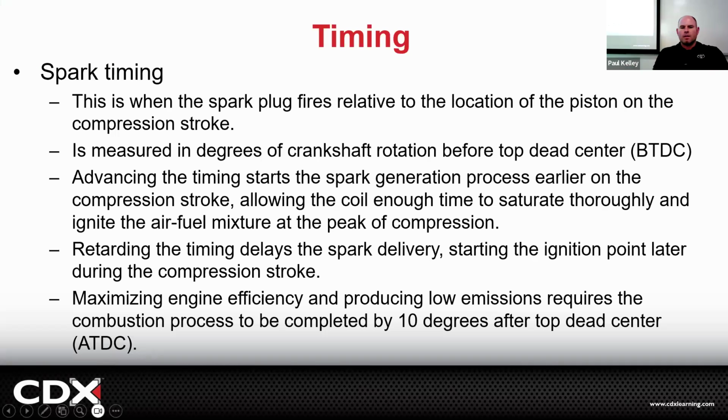So when we talk about timing, it's when the spark plug fires relative to the location of the piston on the compression stroke. It's measured in degrees of rotation before top dead center. So if you think of it like this, let's make it pedaling a bicycle. All right. If you're pedaling a bike, your feet are like this, right? Let's say you look at your right foot and you're getting up to top dead center, right? Top dead center. And let's say you want to get a good, strong push of that pedal because you're trying to make maximum power going up this hill.